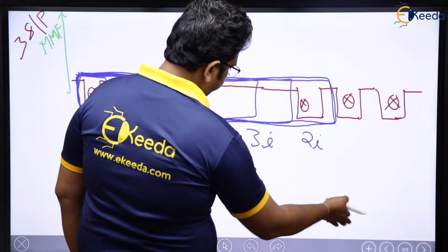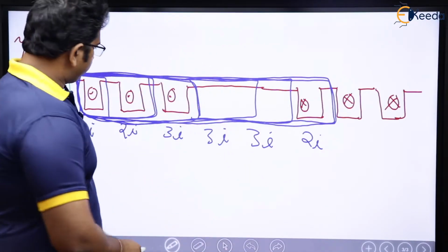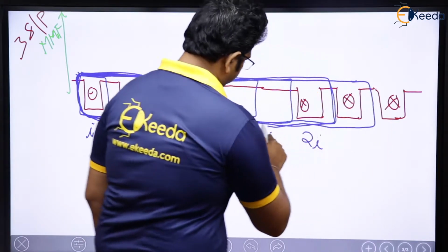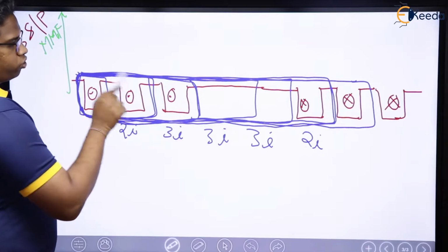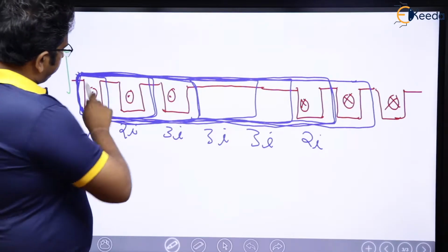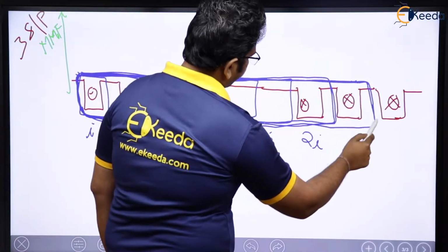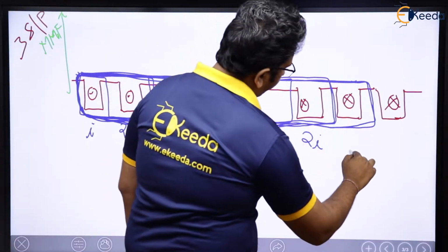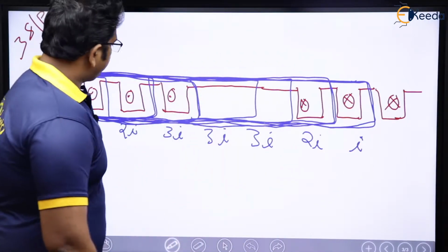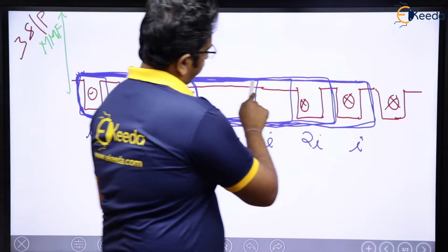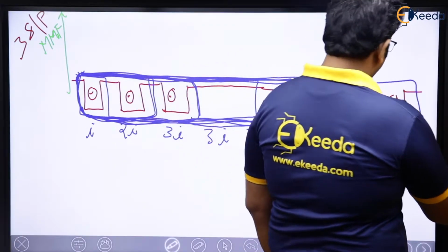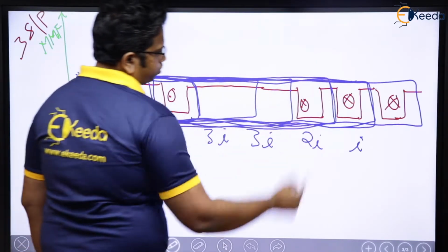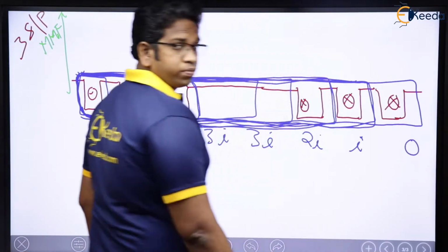Similarly, if you see here, for this closed path, how much is it? It is going to be 3 dots plus 2 crosses, which means 2 are in opposite. They will cancel. So here I will have only I. Right? And if I think of here, 3 dots and 3 crosses for this whole, so here I will have 0 MMF.